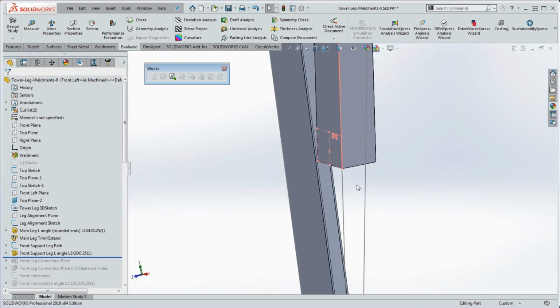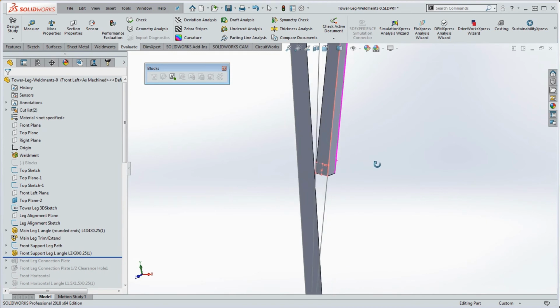So you have to think about that. You want to make sure that every other element after this is going to have a reference to existing geometry. The existing geometry over here is going to be our main tower leg. So this kind of goes along with the concept of stacking your elements together. These two have to come first before we put in our horizontals and diagonals.